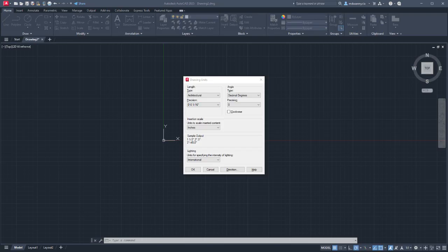So it's going to round that to a different number. I'd say 2/16, but it'll probably round it to an eighth or something, for example. Keep that in mind. When you enter a number that is below that precision, it will get rounded to a different value.